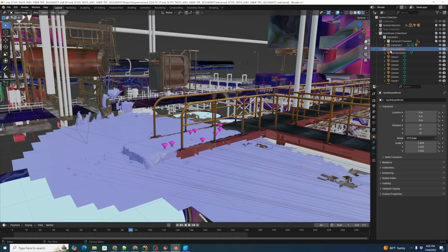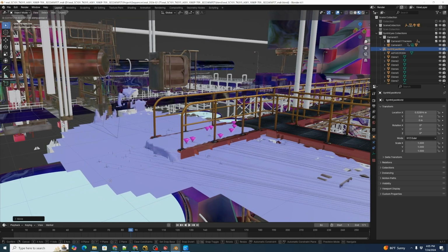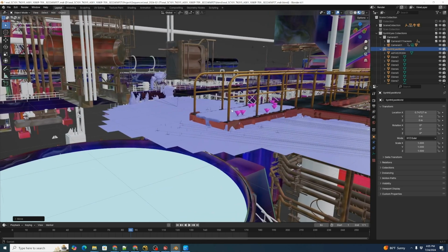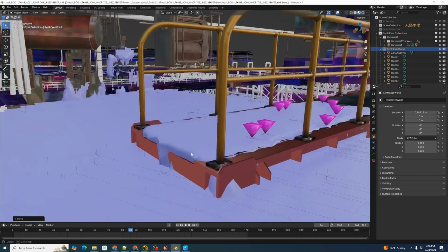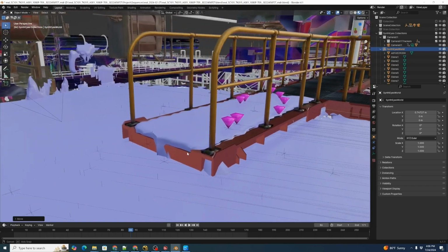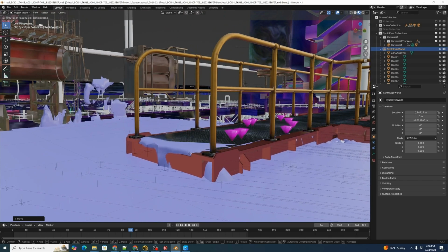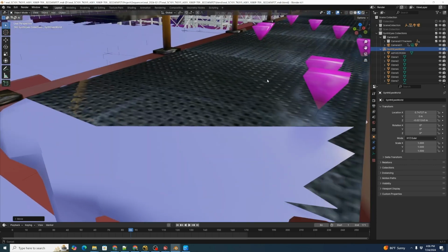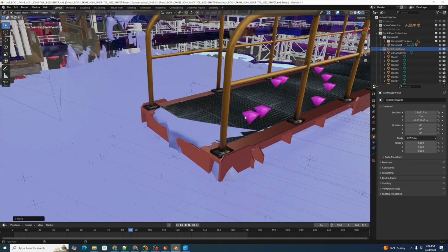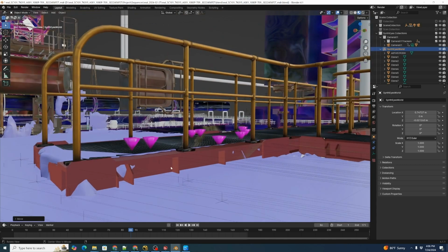And we're going to highlight our Syntheyes world null and hit GX, Blender's usual move command. And what we're doing is we're moving it so that the edge of our physical scan, which correlates with our actual live action world, is going to line up with the edge of our CG world. And that way things are going to all line up correctly. And we can click GZ to bring it down a little bit until the edge of our markers here are just in contact with the top of the CG world. And we're going to want to align these closely. So this is pretty close, but you'll notice back here that our markers are now poking down through there. And we want to make this very precise.